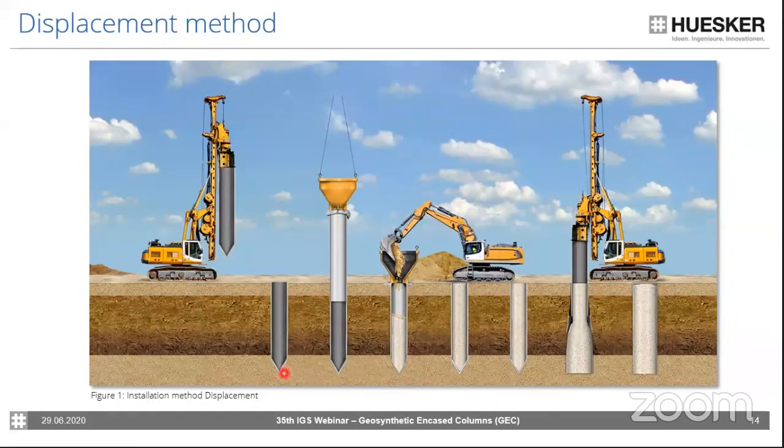After you have driven down the steel pipe, the encasement textile will be placed inside, and then the sand can be filled. When the sand is filled up to the top, the steel pipe can be withdrawn under vibration. And then the flaps at the bottom, which are movable, will just open, and then you can remove the steel pipe, and the sleeve with the sand will stay inside.